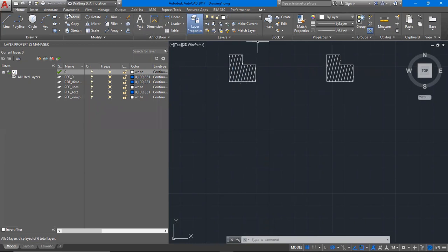So let me rush now to the last thing we will cover today, which is the utilities panel. When I open the home tab, there's a panel here called the utilities panel. This panel contains the measure tool, and there are very many ways of doing measurement: distance, radius, angle, area, volume. You can do all those measurements. By default, it is the distance that is checked. I can check radius as well.